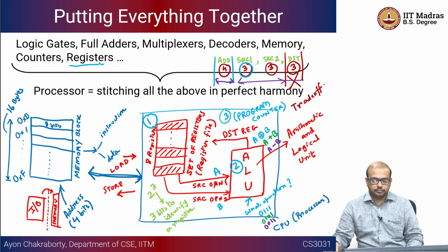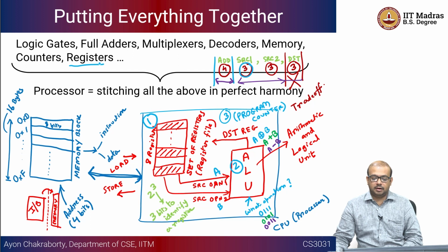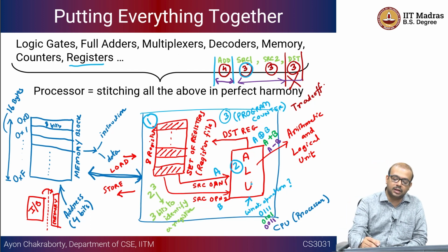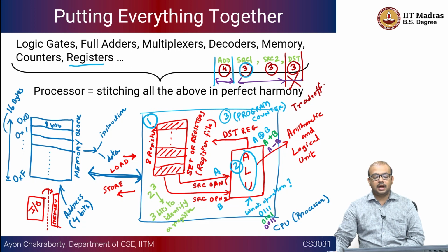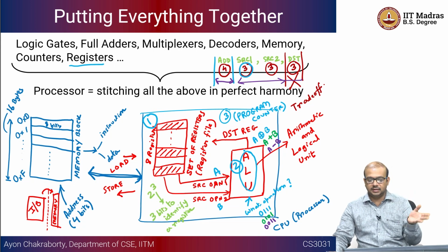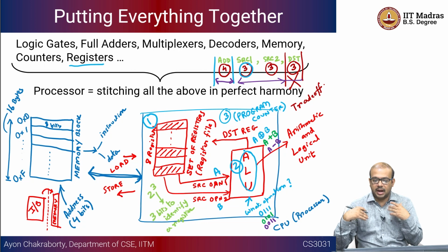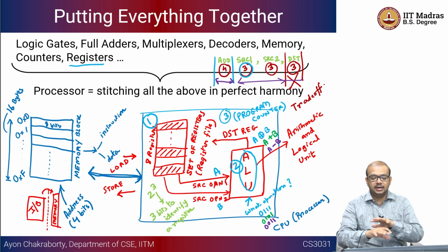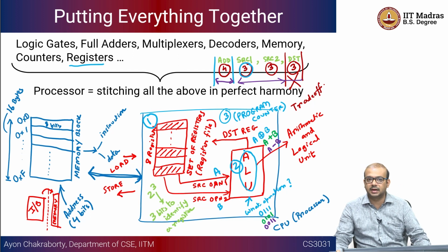One observation that you need to make here, again this is a high level pitch for the processor, right. We are going to look into the actual details of all these things. As you can see, pretty much all the computation gets done here, in the ALU. Okay. So if you remember, I told in the first slide of this particular topic that we spoke about that operation X, which could be an addition operation, plus the interfacing circuit. So the entire thing that we are showing here is your interfacing circuit. All that you are trying to do as a part of this addition is just use a full adder, right. That full adder is something that you have already known from your combinational circuit lectures, right.